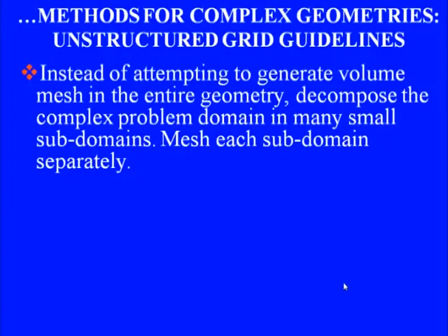For a beginner, it would be very tempting, specifically when you are working with a commercial CFD software which has its own built-in modeling interface where you can generate your CAD model. It also provides you a mesh generator with a variety of options. So there would be a temptation to just click on one of the buttons which provides volume mesh and try to mesh the entire geometry.